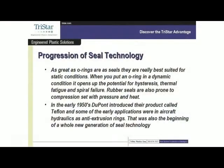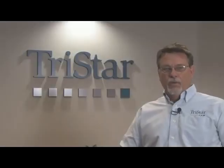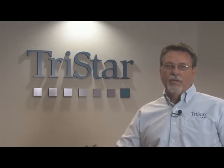In the 50s, we had the advent of what is really the modern sealing technology, and that was understanding that as seal pressures were increasing after the war, pressures were going from 1500 psi hydraulics to 2500 psi hydraulics. And the problem with that is that it started to introduce new problems to those rubber O-rings. We were seeing the rubber turning, rotating in the groove, producing spiral failure and hysteresis and some of the things that can occur.